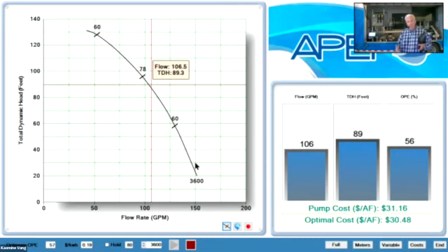You could do that. Now, again, the soft start could help with sanding issues and other issues, cavitation, things like that, so you don't get issues going on. Also, water hammer through your piping. When you start a pump at full speed and it's there in a split second, you can hammer the pipes. I've had pipes blow up before in the field because we didn't have proper ventilation or something, and all of a sudden you had a pipe blow up, and I had a pipe just rip open out in the field before, PVC pipe. So all these things are important. The soft start can assist with that. Okay.